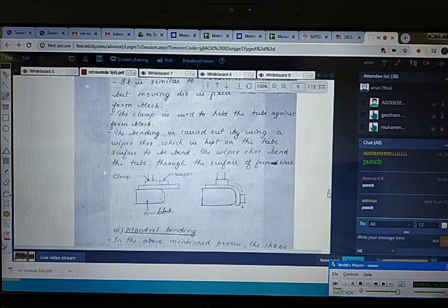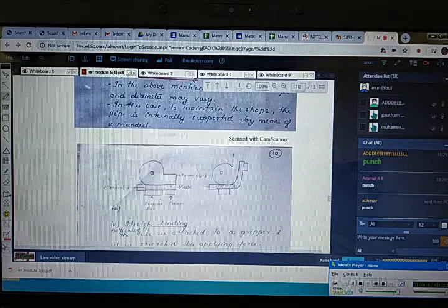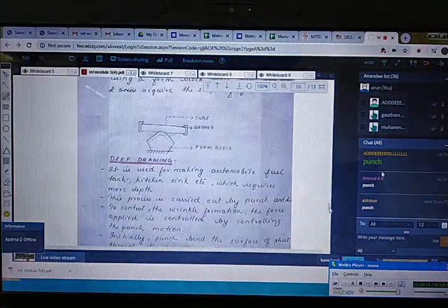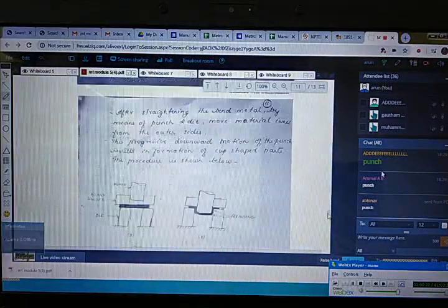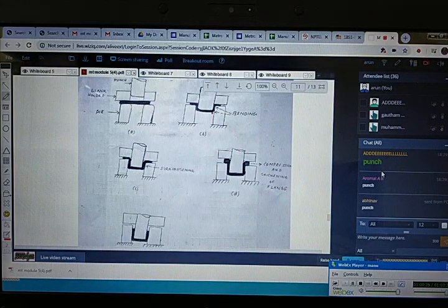And next you can see the neck compression, where it is using wipers by means of repeated motion. Next is a mandrel. Yes, the diameter of that hole will remain constant since it is using the mandrel inside. And next is the stretch bending. And next is the deep drawing. You can see that initially the bending operation takes place. Next is a straightening operation, and last the compression takes place at the flange area. At last the deep drawing is attained.